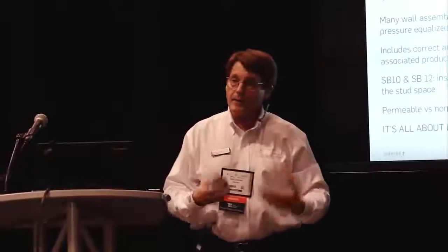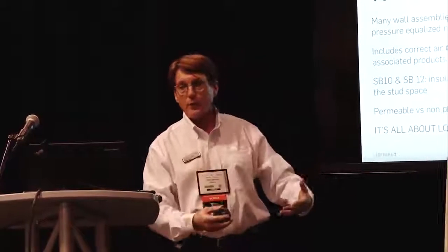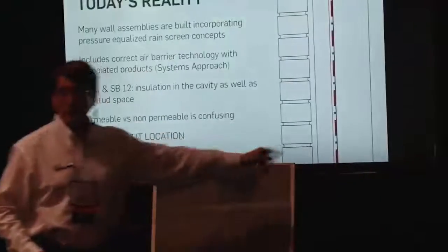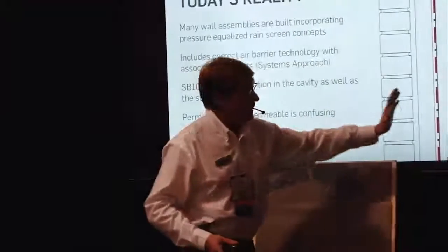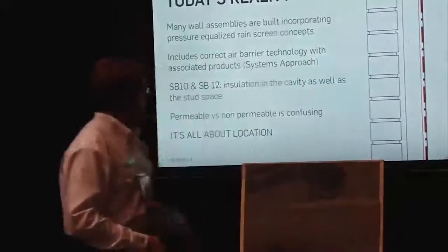And that is a system or a program of understanding. We have a lot of bulk water coming through your wall system. Our air barrier located in this position here becomes the ideal location for your rain barrier. So that's the pressure equalized Rainscreen. Moisture is going to come through, can't penetrate any further. Due to air pressures, we see a lot of drainage.